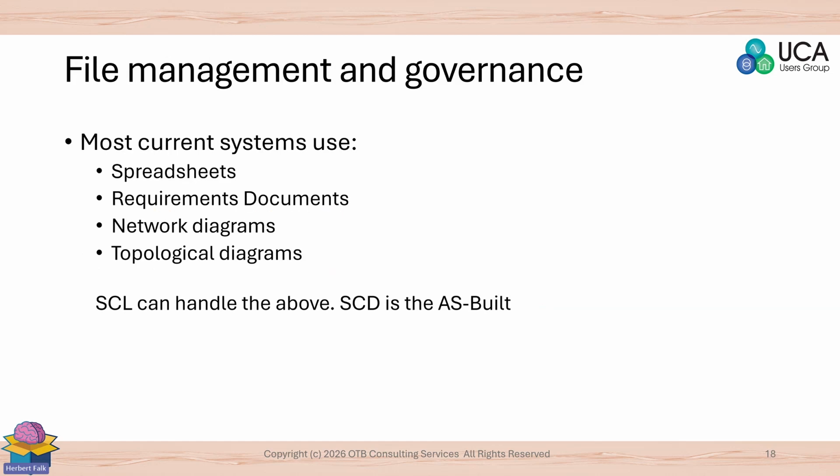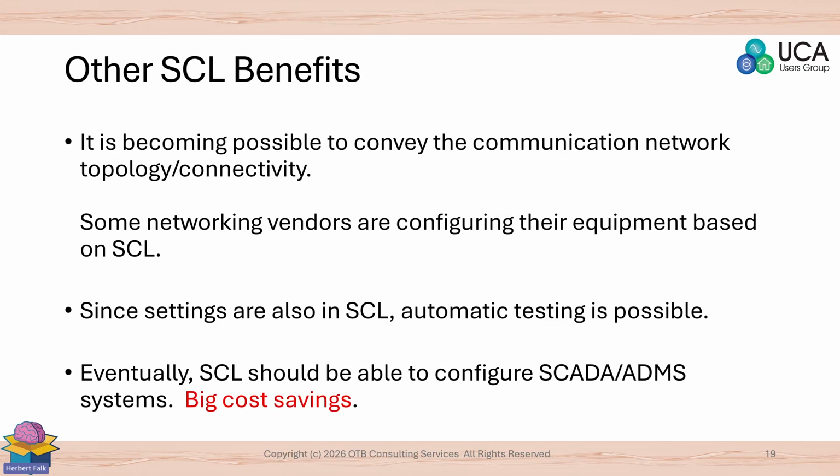So file management and governance, most current systems use spreadsheets, requirement documents, network diagrams, topological diagrams. SCL can handle all of the above, as the SCD is the as-built. Other SCL benefits, it is possible to convey the communication network topology and configuration settings.